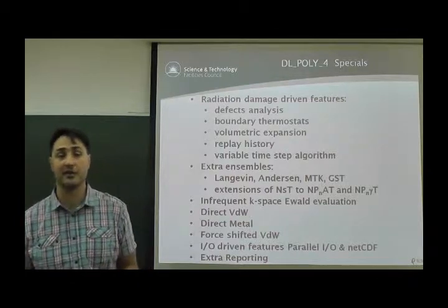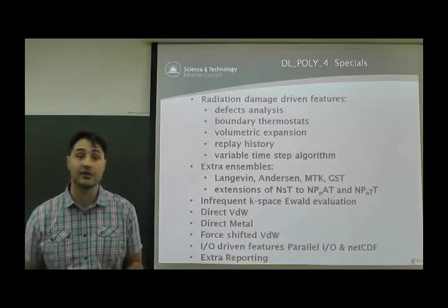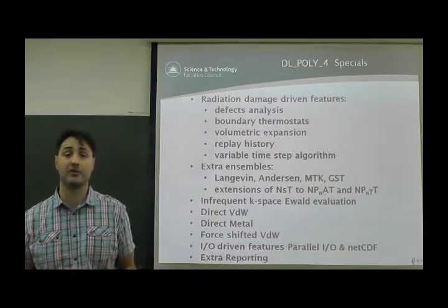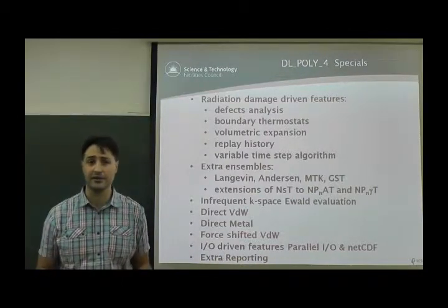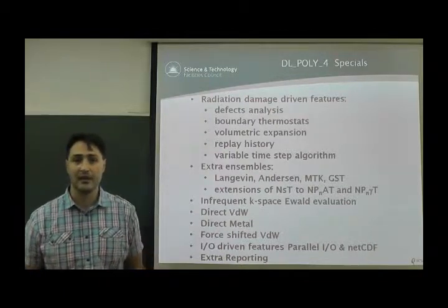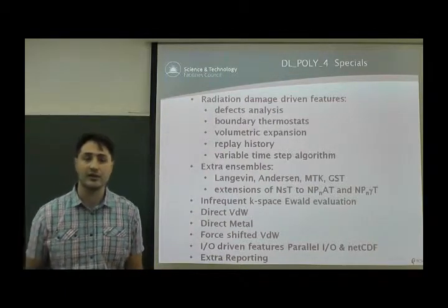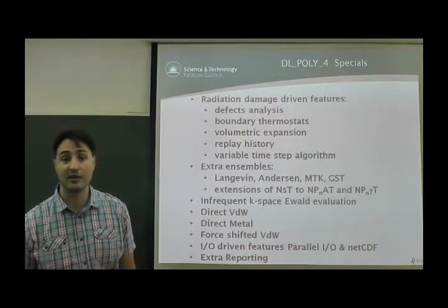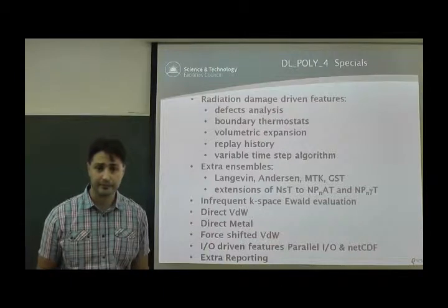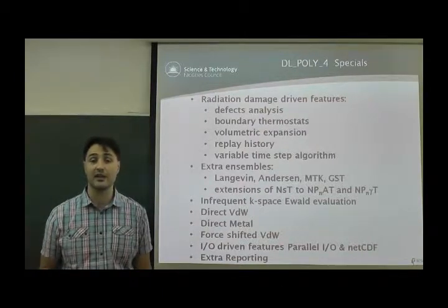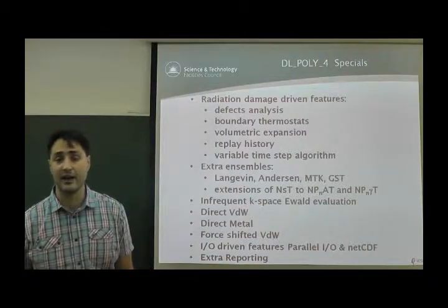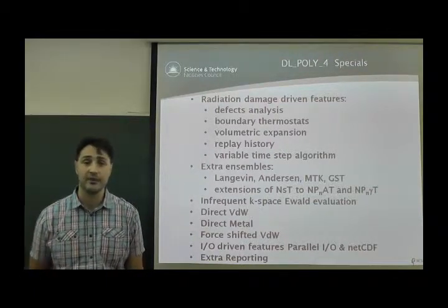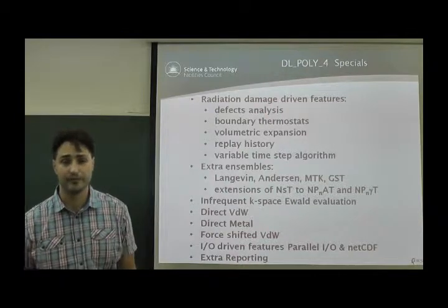There's some specific features that I have developed over time, such as radiation damage defect analysis, boundary thermostats, volume expansion, replay history, variable time step, and there are some extra ensembles that don't exist in the DL Poly Classic, like Langevin, Anderson, Martyna-Tuckerman-Klein, and gentle stochastic one. There's also infrequent k-space event evaluation, direct evaluation of the Van der Waals and metal potential and forces, and we have parallel I/O.